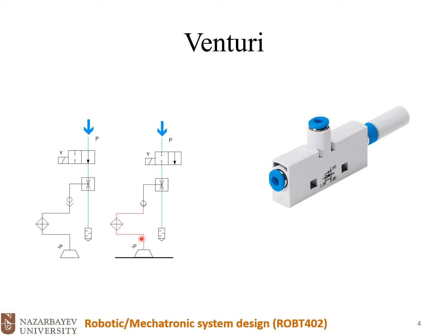Okay, so now this port is closed because the part is already picked, and since the part is picked and we have this non-return valve here, we have a negative pressure here. Okay, and now the pressure will also increase at the Venturi, and the non-return valve will close the pathway to the suction cup.